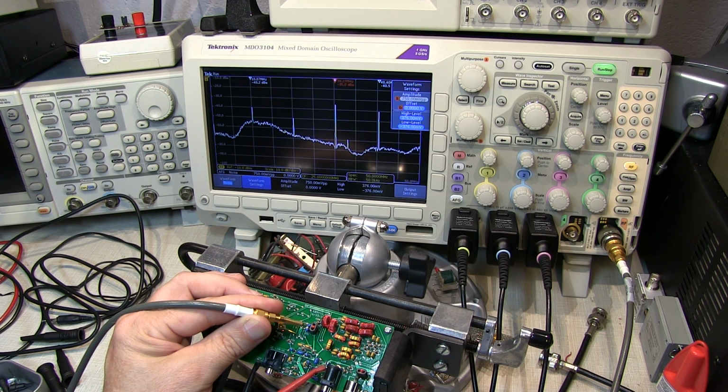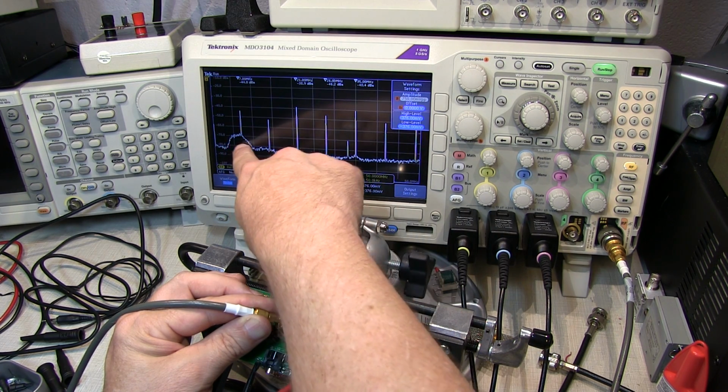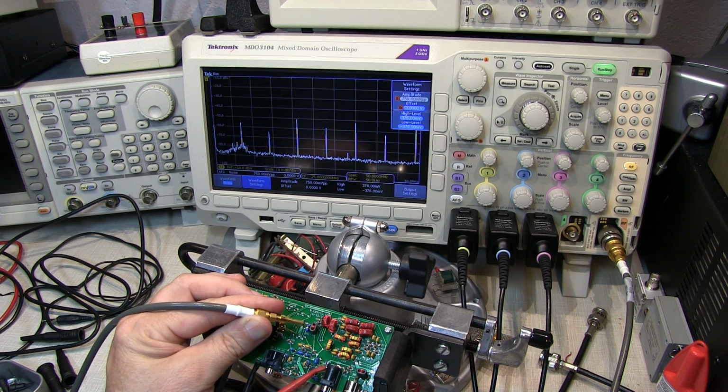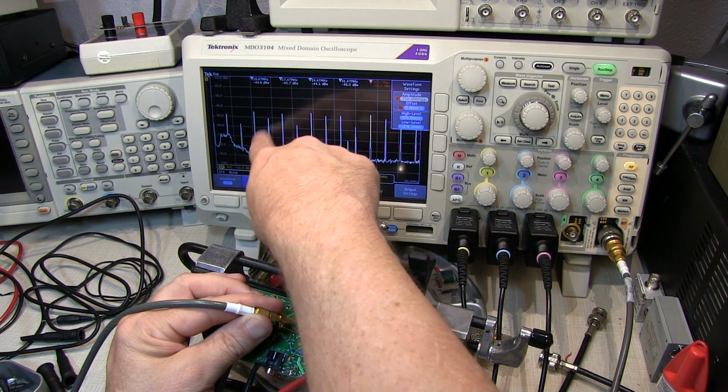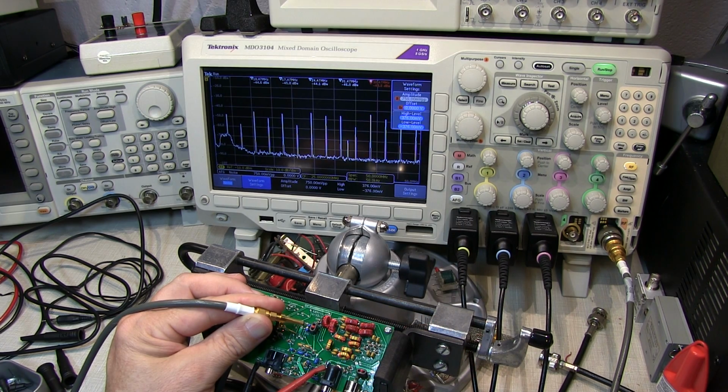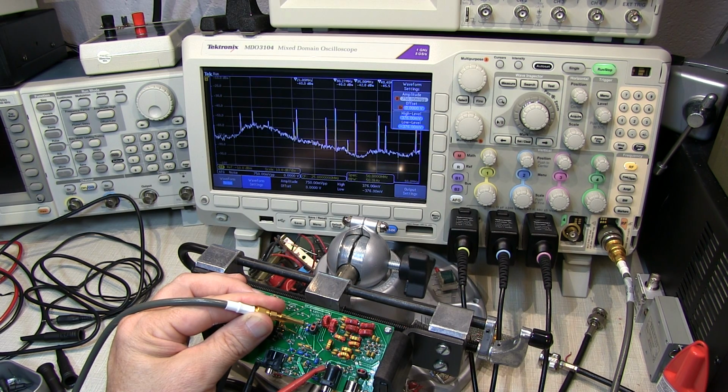The next band down is 4 to 8 megahertz, and we'll see that down there. We see the whole noise floor drop because we're going through the attenuator in that case, but I can see that bandpass characteristic right there. I'll put the probe back on there and switch to the lowest frequency, and you can see the filter shape change down there. And of course I can see the clock feedthrough that I'm picking up off the board here. I'm not too worried about that, but I'm seeing the proper filter shapes as I cycle through these various filters. So we know that part of the circuit is working properly.